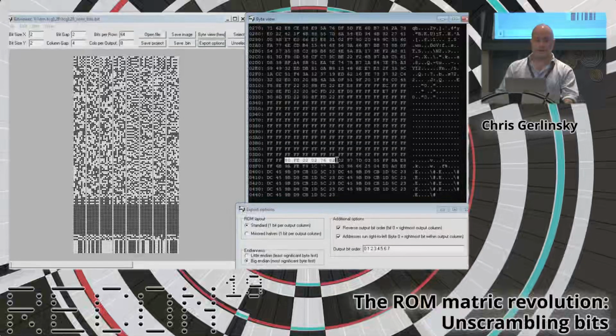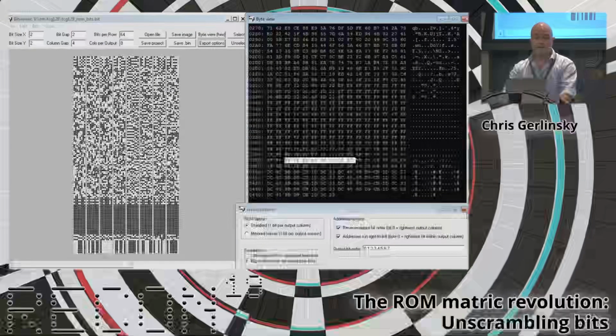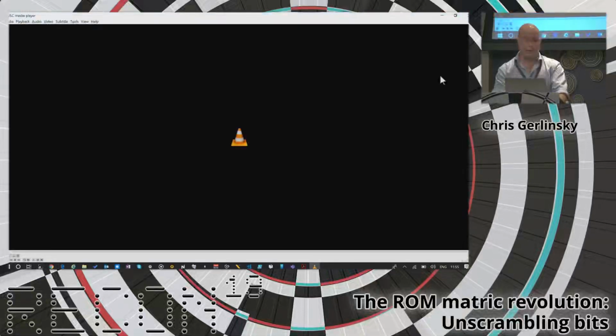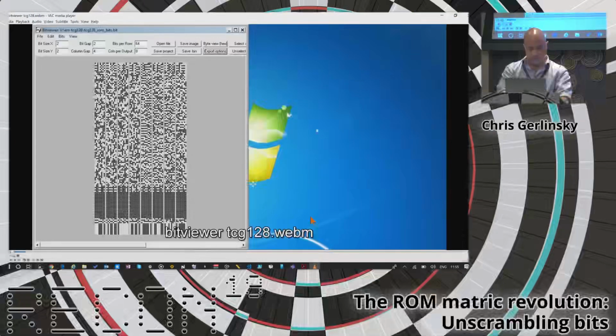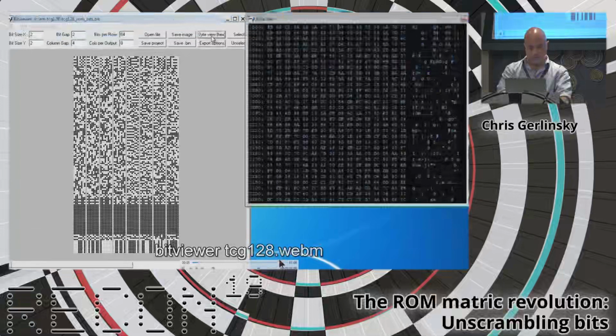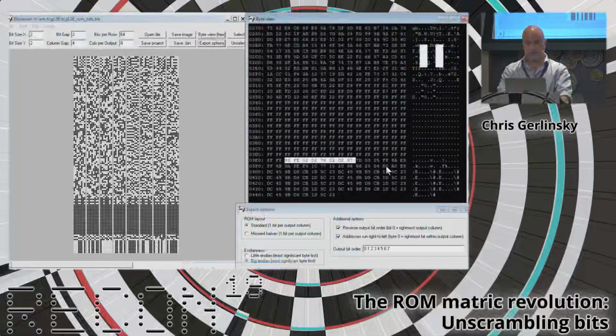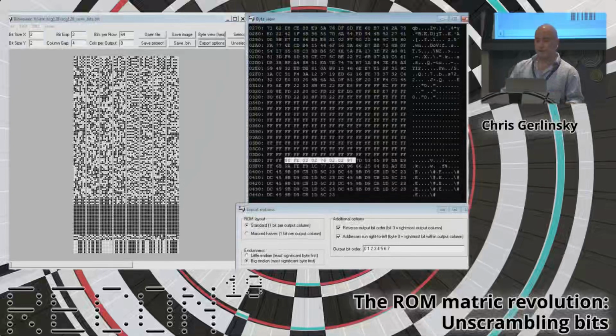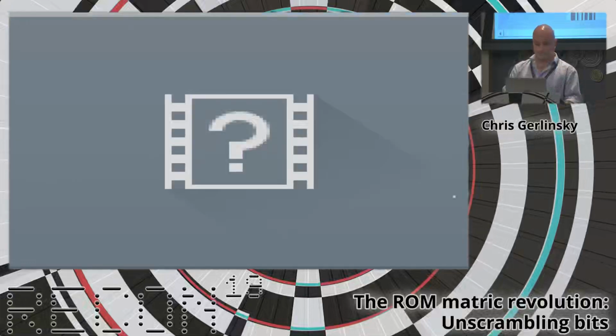And then after doing that, the next thing I'm able to notice is there is an 8-byte sequence that appears to be plain text. That was valid 8051 code. There was an infinite loop there, which is a pretty common thing to see at the end of code blocks. The ADFE is an infinite loop, followed by some long jumps. There's sort of a vector area. So there's 8 bytes that turned out in plain text, but the rest of it still isn't valid code at this point in this chip.